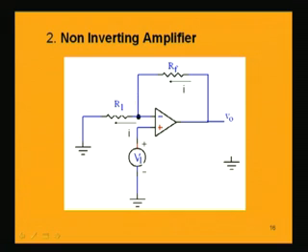It will not be entering the op amp, as we know that this is an ideal op amp analysis, and the current entering into the op amp is 0. So, it is bound to flow in this direction to the ground. The same current will be flowing through R1 to ground because there is no current into the op amp.